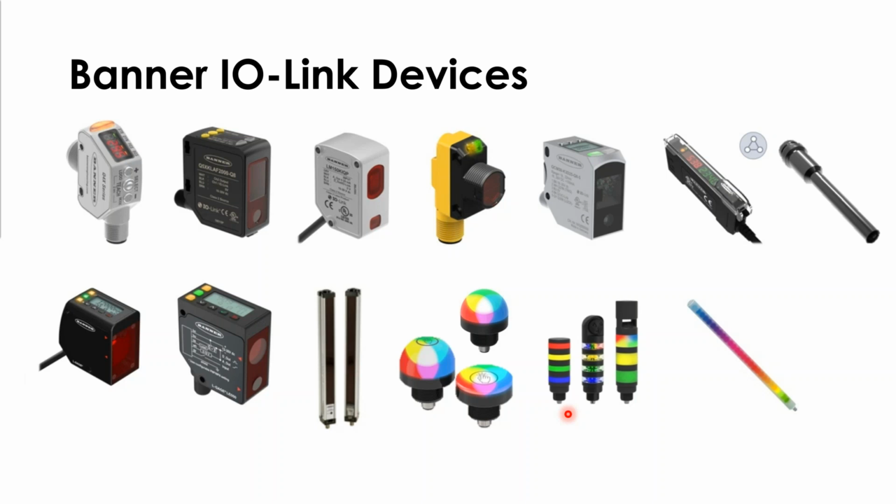It's got an actuator, so now you can also use this as your push button for your operator. Again, all with one IO-Link device. And here it'll start to do some of the rotation and things like that. And then we'll hook up to this photo eye and kind of get an idea of what the heck we can do with a photo eye over IO-Link.